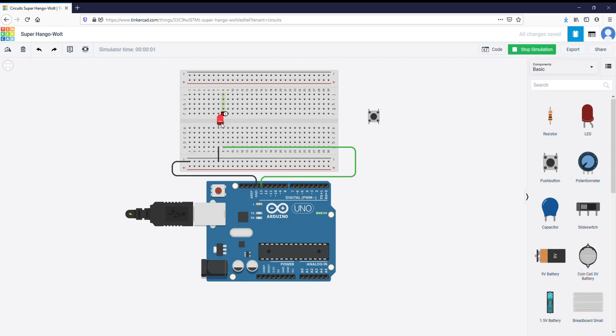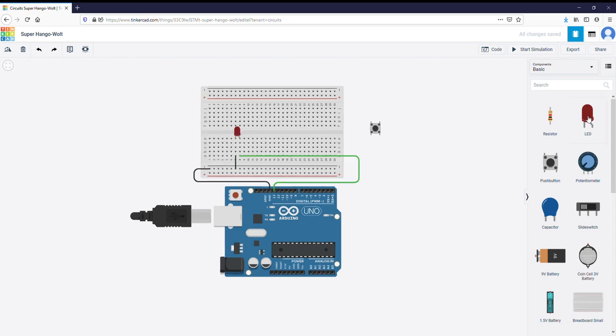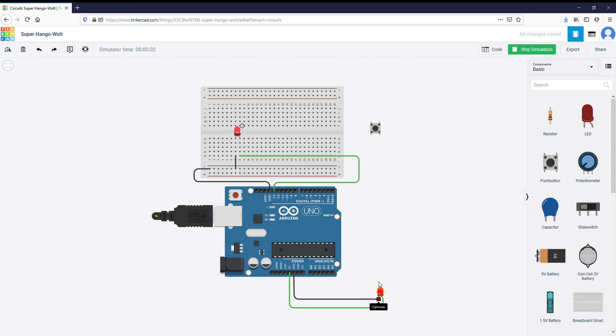Oh, it's not blowing up, but you have a warning sign, and it's going away, so it's not easy to read, but probably it's going to say, hey, you're exceeding the maximum of this LED. Or maybe we can try another one, because it also has a 5 volts power source that comes out. So why don't we directly connect it, and this one goes to the ground. This is something that I didn't plan to do, but let's see. If you run it, oh, the LED has just gone. This is burnt, and it's cute.